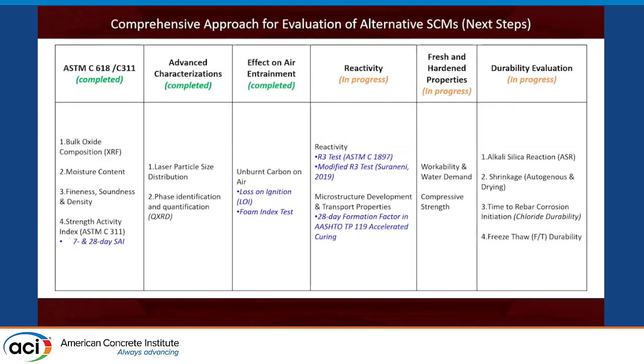However, we only address ASR here. But I'm working on this 6-year project with Texas DOT. We developed this whole aspect as an Excel tool. You give input, and it calculates based on CST how much you need for ASR. It also calculates the shrinkage-based cracking potential. It also predicts the corrosion. It also predicts the freeze-thaw durability in terms of critical saturation.